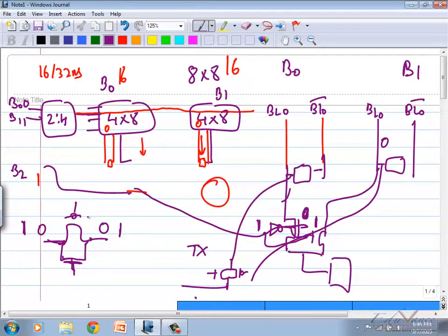Look sir, the number of row enables, the number of NMOSs you see is more, so your decoder complexity will reduce but the sizing will increase. Then you will have a column decoder as well. Understood? Yes or no? Understood? Anyway, SRAM is an interesting concept. Correct? Yes or no? Clear?